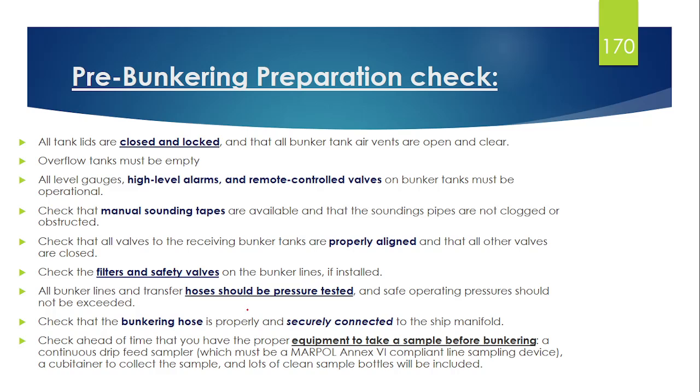So now let's see step by step what we need to do before bunker, during bunker and after bunker. First start with before bunker. Now if you are going to take a bunker, you have to make sure these points are checked. The first thing you have to check is all the tanks. Suppose you are taking bunker in one port and one starboard tank, like this is the cross-sectional view.